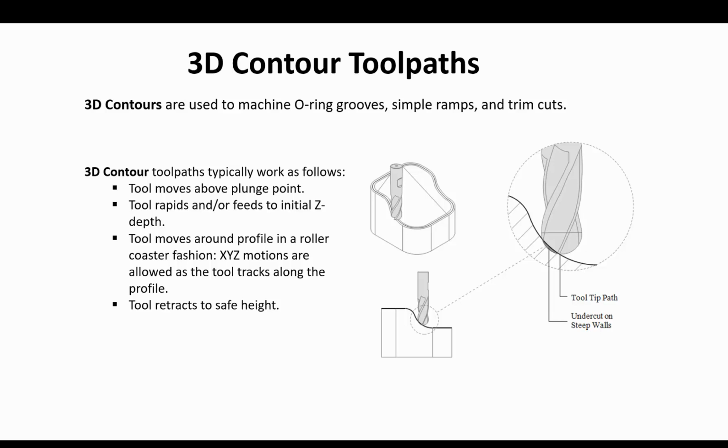When a 3D contour is selected, Mastercam automatically sets contour type to 3D and activates the maximum depth variance field. Cutter compensation for 3D contours is more complex than 2D compensation, and simply following a 3D profile with the tip of the cutter will gouge the part as shown in the figure. Accurate 3D profiling is accomplished using a surface or a solid machining toolpath.